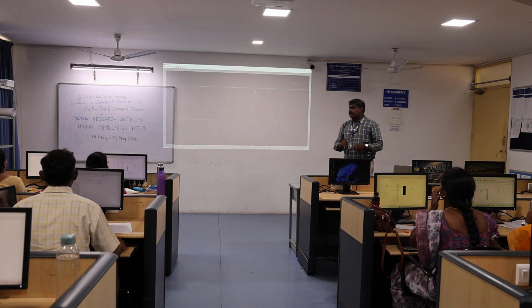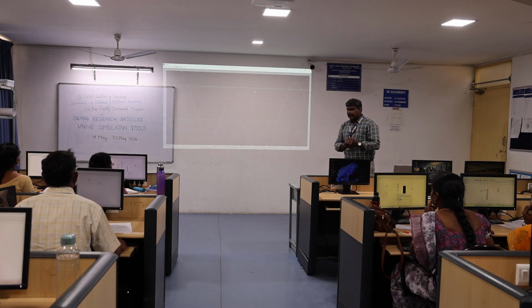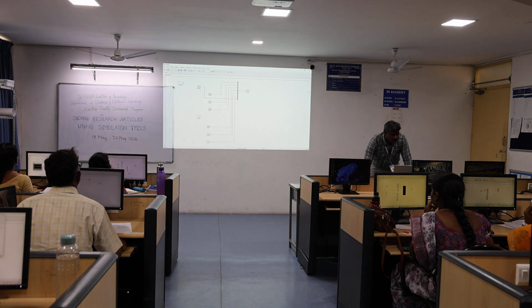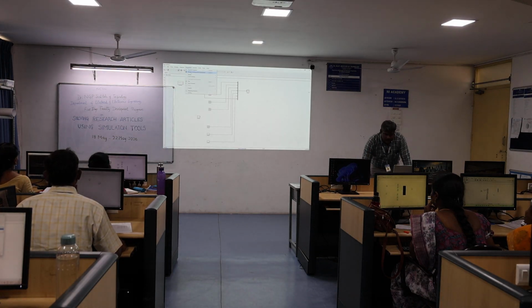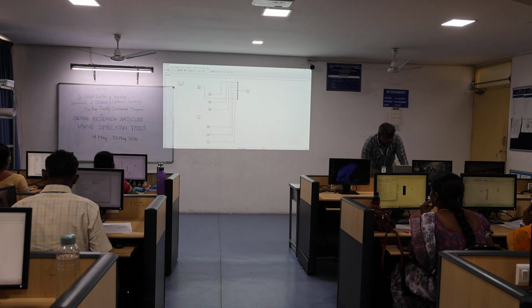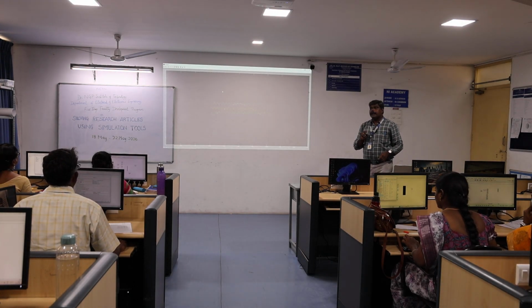Why? Any idea? Most of you know about MATLAB. But here we have given all the values, but the triangular is not properly generated. Okay, right. Now, whenever we are going to use the triangular signal, go to the model configuration parameters. Here you can apply the maximum step size, 1e power minus 7. Next again 1e power minus 7 based on our switching frequency. So again initial step size, now apply, now you can generate. Now see here your triangular is properly generating now, right?